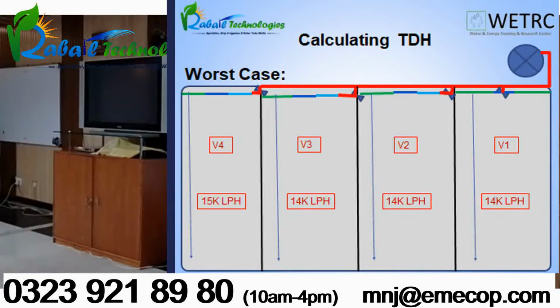So while looking at this case, I would prefer to calculate the friction losses for valve number 4 and forget about valves 3, 2 and 1, because we have the highest flow rate and the farthest point from the pump. The farthest point from the pump is V5, V4, right?